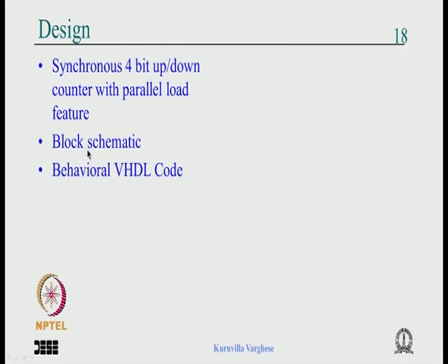Okay, and what we will do first is write the block schematic, then we will write the behavioral code systematically from this block schematic. So you know that the 4-bit counter needs 4 flip flops, you have the clock and reset. So when the reset comes the count is 0, and when the clock comes the game starts.